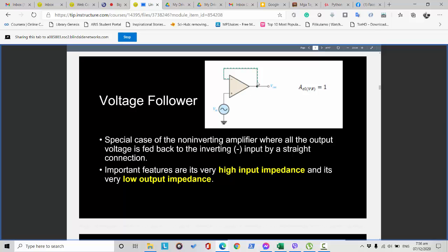So basically, this operational amplifier circuit has an output voltage that directly follows the input voltage, that is, the output voltage is equivalent to the input voltage. Whatever the input voltage is will be the output voltage, and this circuit does not provide any amplification.